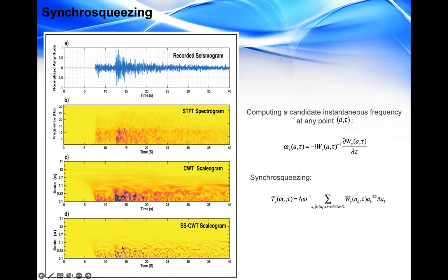So now we will use this characteristic and perform the thresholding just along the ridges, or these curves, which are the main elements of our signal. So now instead of processing hundreds of traces of wavelet coefficients, we just need to threshold the coefficients along only several of these curves in the synchrosqueezing domain, which would increase the efficiency and speed of our denoising process.